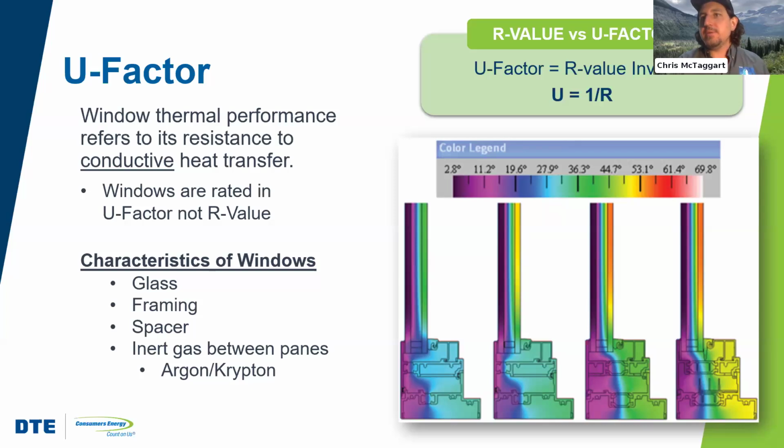So incrementally, we're improving this window. Let's say we're changing the overall glass geometry in the next one over to the right. Well, now our glass surface temperature is closer to 50, warming up a little bit. Still, our frame is not very warm. Okay, now we're going to add an inert gas. And so our window glass is performing better. It's up to 60. That's maybe passable. There are a couple cold spots still, though, where it drops, especially closer to that spacer.